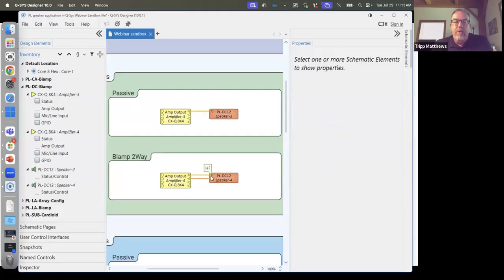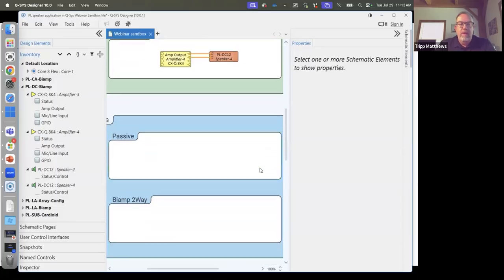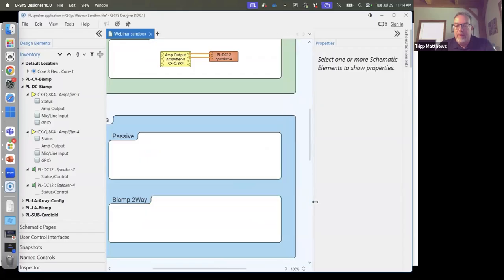And it is telling you what's on what path, just in case you needed to know, but the crossover and everything is truly happening in the speaker block. So no need for any upstream high pass filtering and crossovers or anything like that, unless for some reason you wanted to make a change on that crossover yourself. You could, but this will default and have our own needed crossovers built in, just allowing you the separate power to adjust some HF and LF balancing. All right, let's shrink this back a little bit.